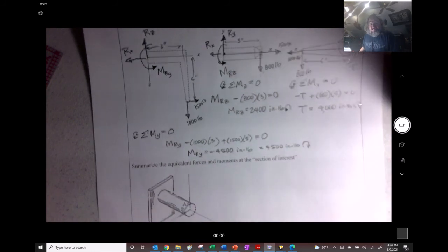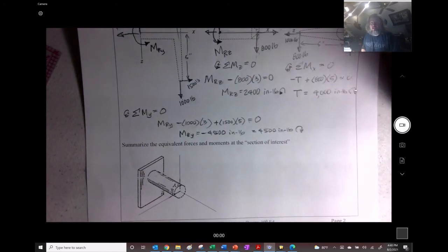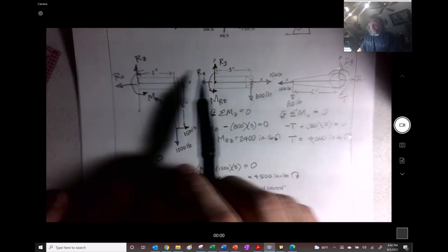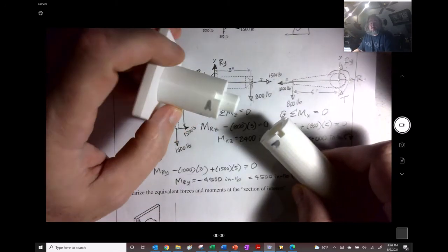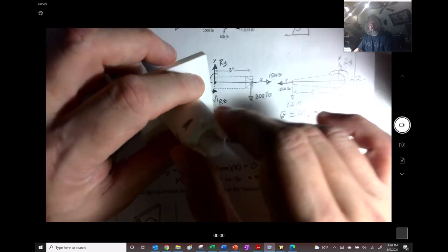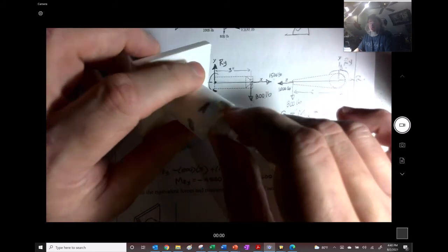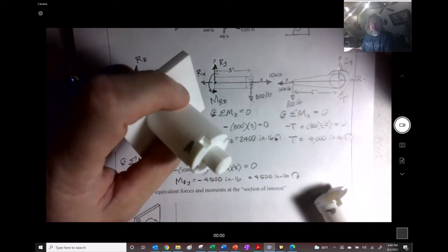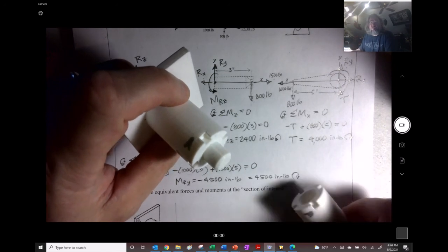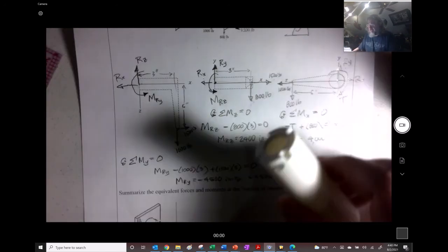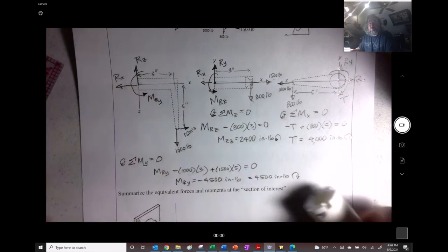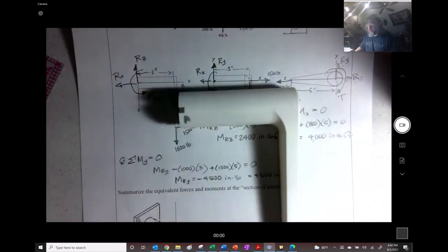All right, so a last step that I like to do, and I really encourage you to do it, is to now, instead of drawing the forces onto this piece, move them over to this piece. Because this is usually where I think we want to analyze the stresses. And we will see in class 2, I'll use the same example, and we'll pick this apart and think about the stresses that are caused by the statics. But this is a class dedicated to just learning, refreshing on statics. So these are reactions. These are equivalent forces and moments. Reactions on the free body diagram, reactions to the loads.